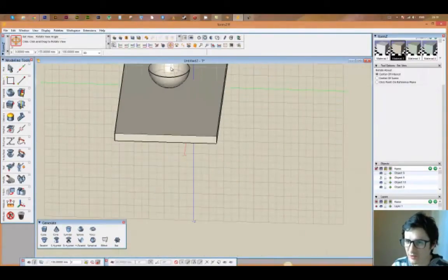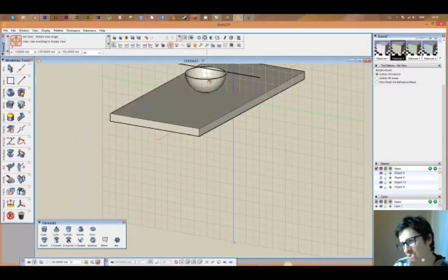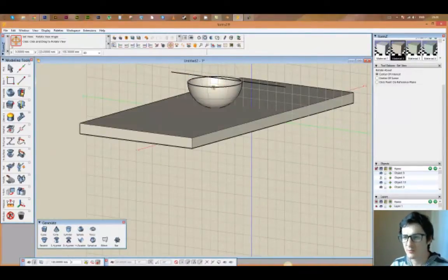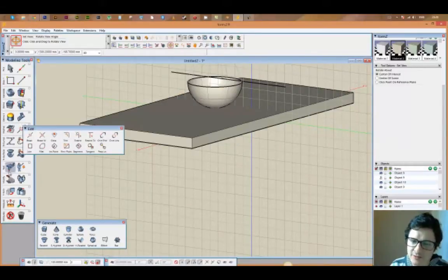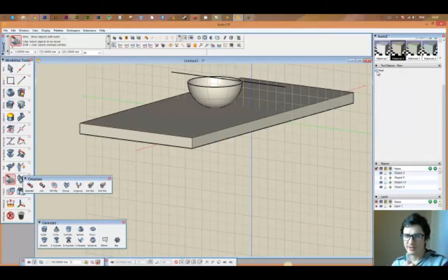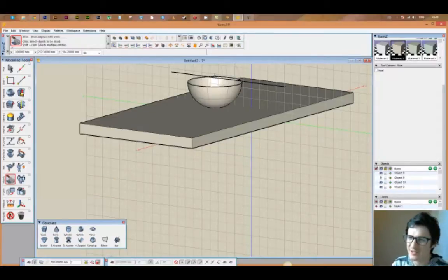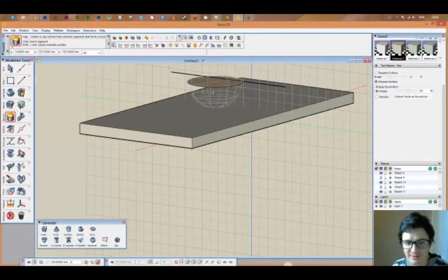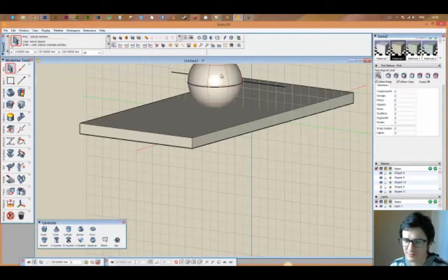Now, one thing you've got to be careful of is that I want to have two different kind of pieces for my orange. So I want to have a separate top piece and a separate bottom piece. And if you had used your slice tool with this checked, it would automatically cap it, but I don't want to cap it. I just want to leave it unchecked. It'll just make texturing a little bit easier if you have separate faces. So I'll just leave that unchecked and then add in a cap using the cap tool. So just cap that. It'll ghost that. So what I'll need to do is just unghost the bottom half and, sorry, oops, redelete the top half.